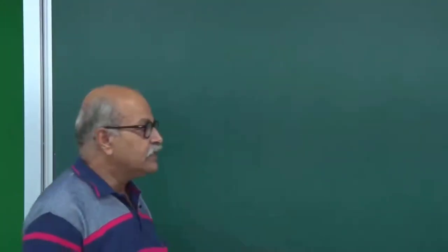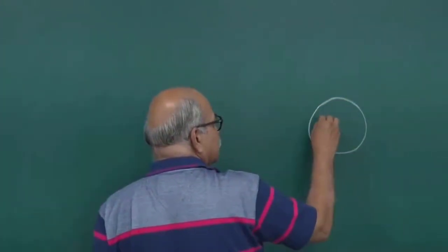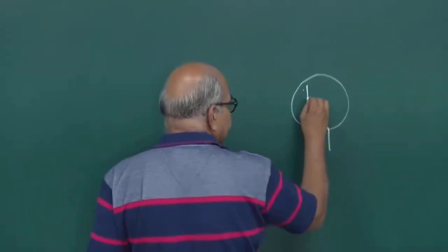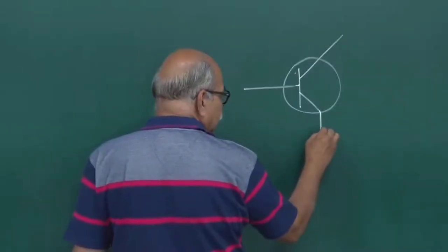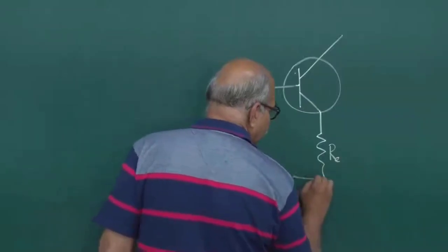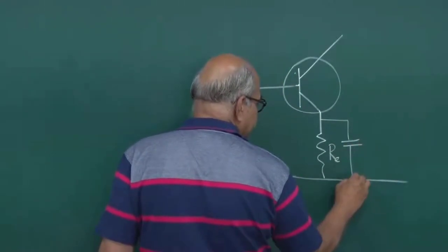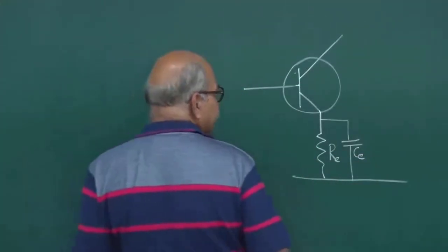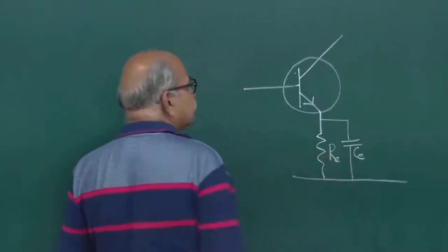So, in a transistor amplifier in common emitter configuration, you have this emitter here and collector here, base here. Then you put this to ground, with some resistance. In the actual case you also put some capacitor, so that the alternating signal is bypassed from here. And then this side should be forward biased, and this is an NPN transistor.